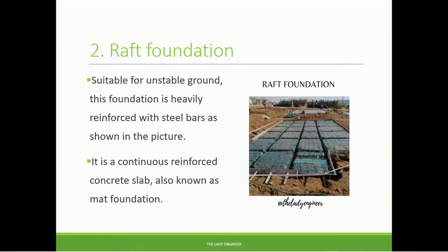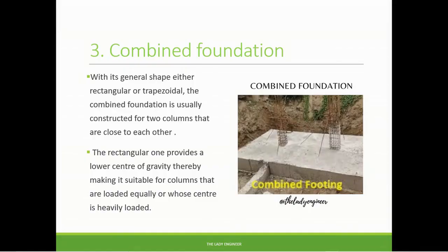It is a continuous reinforced concrete slab, also known as mat foundation, and obviously just from the picture, you can tell that this type of foundation is quite expensive. I mean, you have to use a lot of steel. It's more expensive than several other types of foundations like the strip foundation.